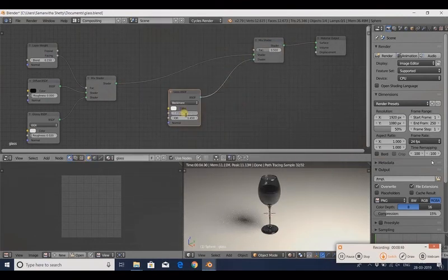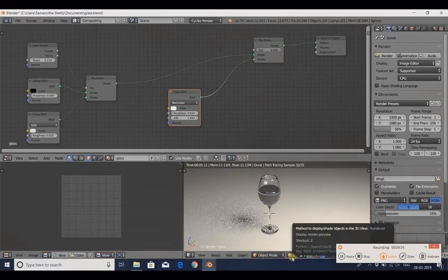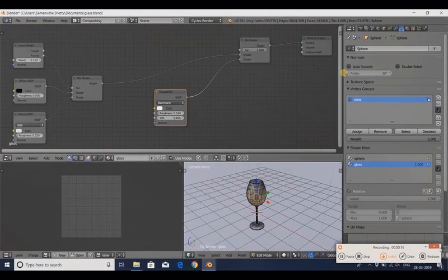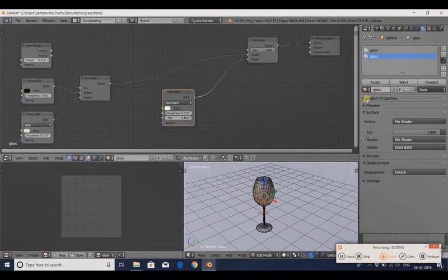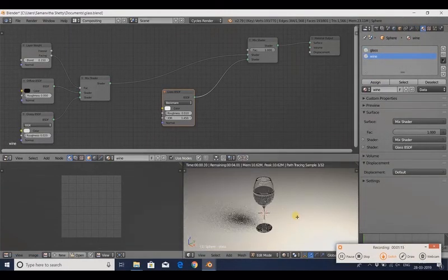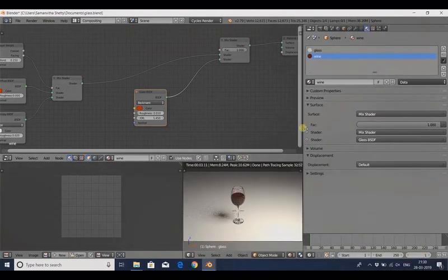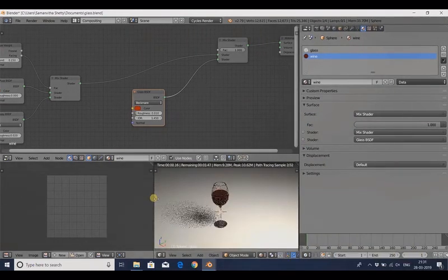Now let's make the surface smooth. Let's add a subdivision surface modifier. Set the view and render value to 2, then click the smooth button. Next, add a surface for the glass to sit on. Now, add a mesh plane and drag it to the bottom of the glass and then scale it.